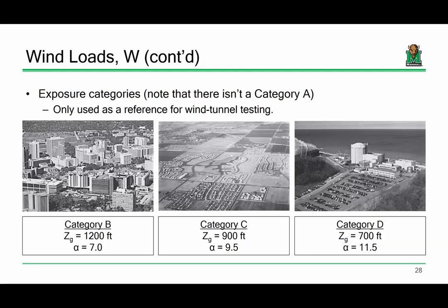And you're only going to do wind tunnel testing if you got a really unique structure, like a really tall structure or what have you. The spec actually allows you to build sort of a scale model of your structure and instrument it with strain gauges and whatnot and put it in a wind tunnel and then measure the strain and say, okay, well, that's my forces on the building. And you can do that, but it's pretty expensive, and you would never do it unless there's a reason to do it. If you're doing a regular old everyday structural design, you're never going to do that. If you're doing the Burj Khalifa, yeah, you're going to do wind tunnel testing. So it just depends on your project. If you have something really weird, you go forward and do that.